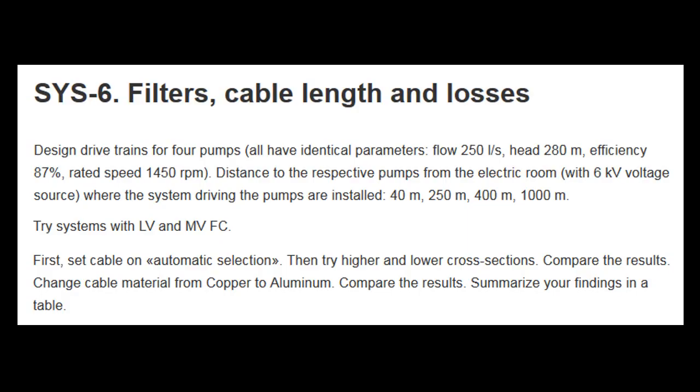So watch out for the length of the cable. If the cable is very long, then you should use a special filter. If you are not familiar with the filters, please read about this in the electronic textbook or on the internet. Another aspect is cable selection. You can play with the number of runs for the cable, the cross-section, and even the material of the cable.